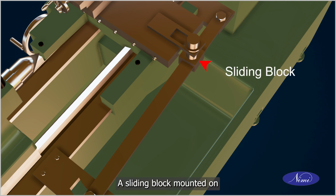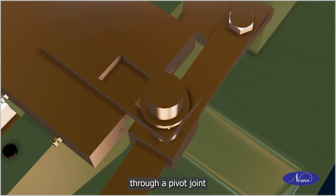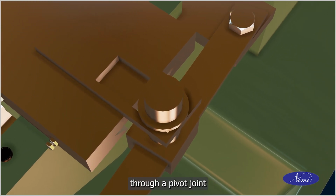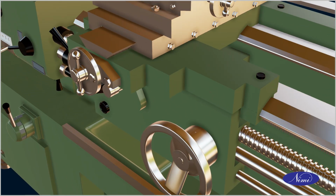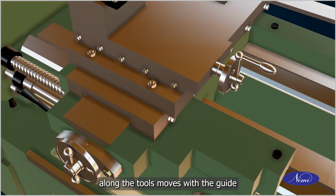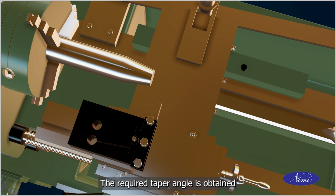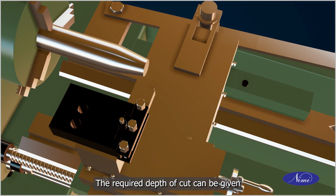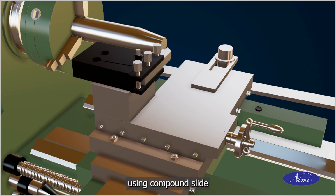A sliding block mounted on the guide is connected to the cross slide through a pivot joint. The cross feed is disengaged. The cross slide along with the tool moves with the guide. When the position of the guide is changed by an angle, the required taper angle is obtained on the workpiece. The required depth of cut can be given using the compound slide.